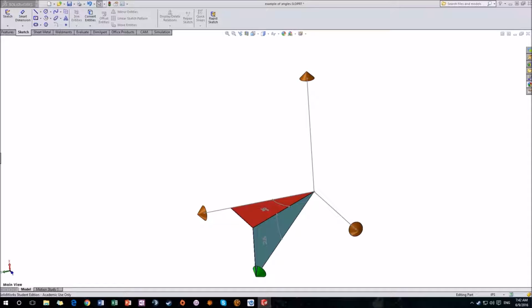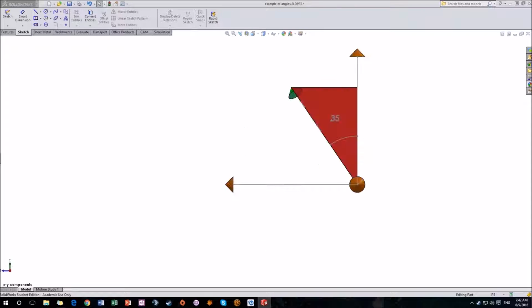I usually call that strange leg my force prime value or my force xy value because it is an intermediate step to finding the final components. Now to find our x and y components is pretty simple. Here we can see solely the red triangle, which has our x and y values. And of course it has our force prime or force xy value from previously.